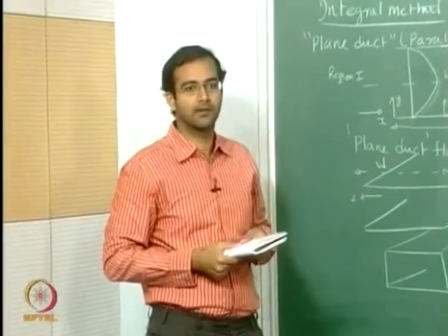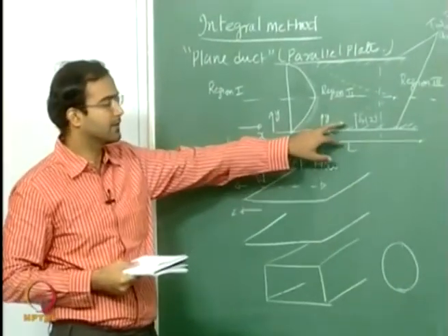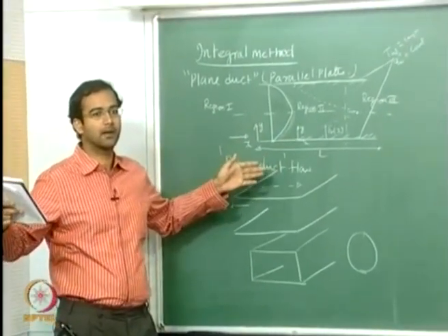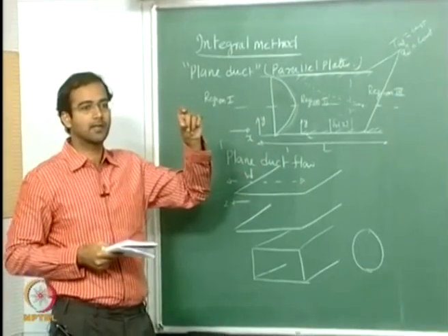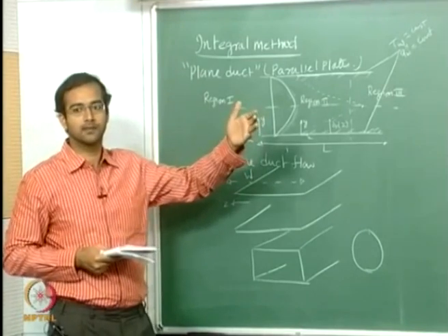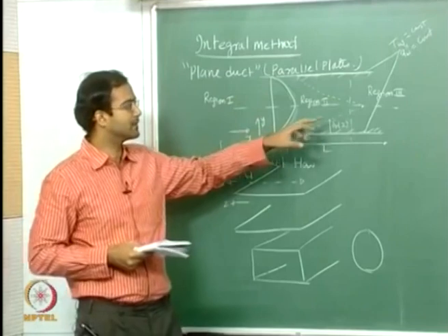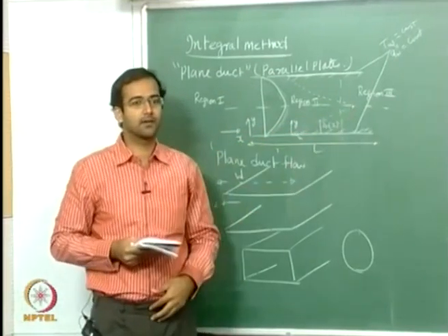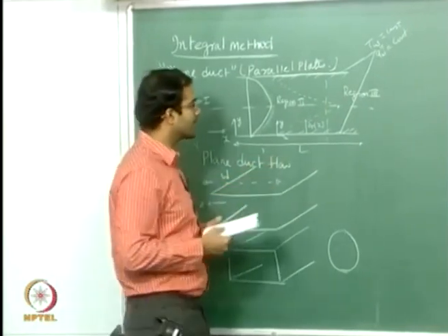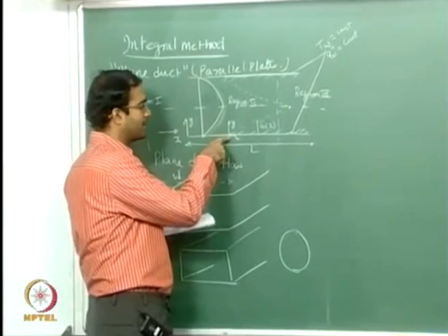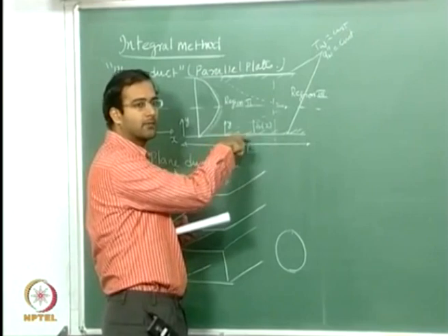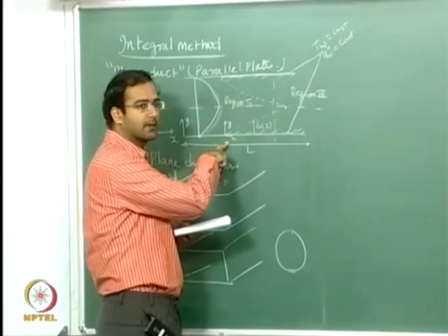by viscous effects. So a boundary layer, as the definition goes, is a region which, if you look at the total length of the plate compared to that, is very small, so your delta by L has to be very small, and away from the boundary layer the flow has to be inviscid. Once the viscous effects start coming, then the definition of your actual boundary layer approximation will not be valid. So therefore you can see within region 2 it can be applied from the start of the boundary layer to a certain distance downstream. So these momentum and energy integral approximations can be valid.